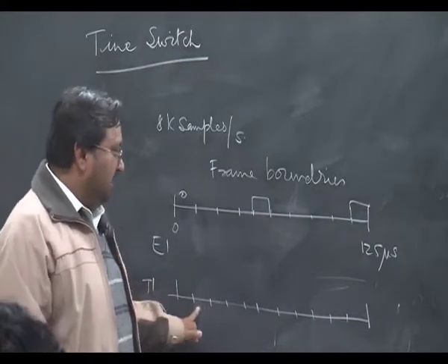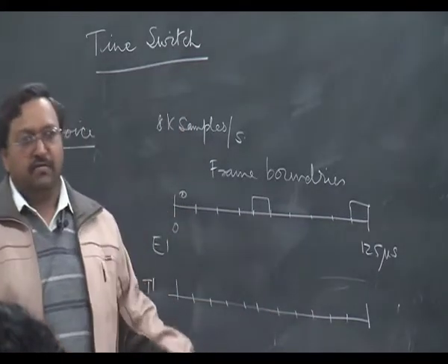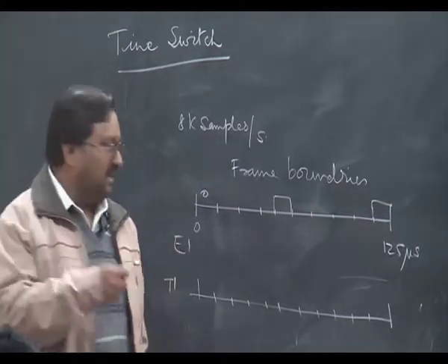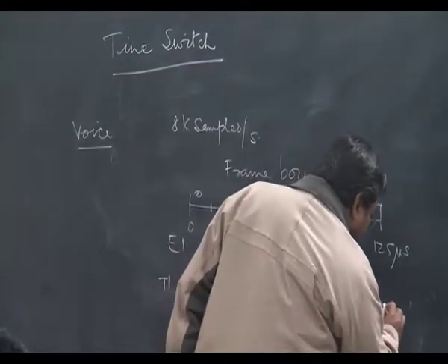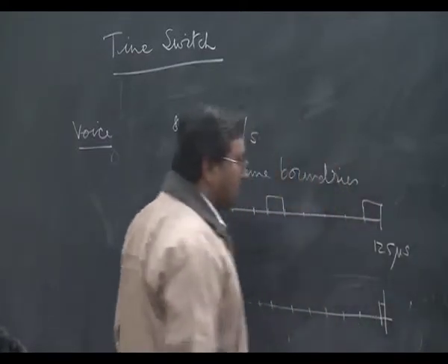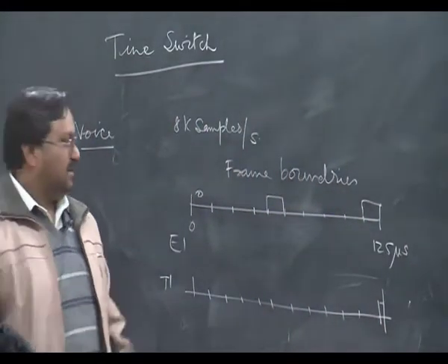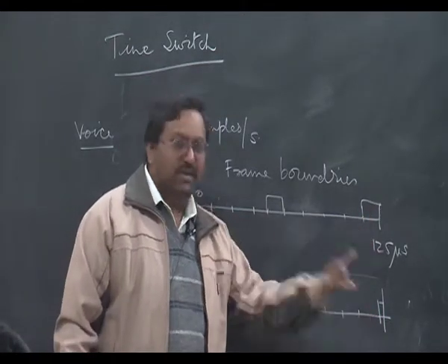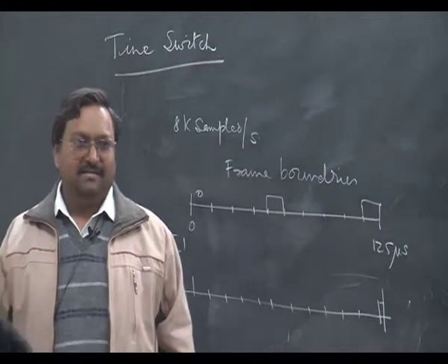In the T1 case, there is no octet reserved for signaling. Signaling is done in a different fashion. Here one extra bit is used for framing. In E1 the whole octet itself is used for framing, while here only one bit is added.